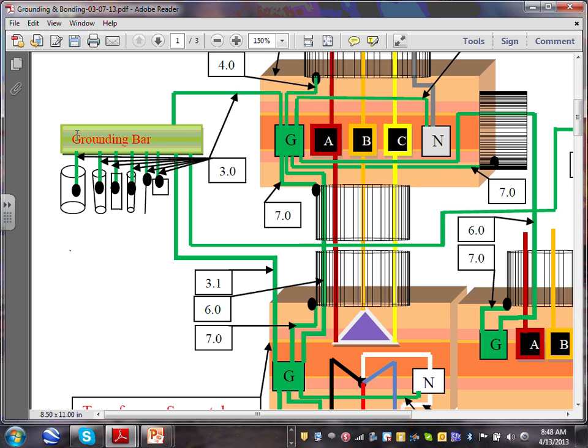So what I thought is to have, I'm sure you guys are familiar with a grounding bar. What they do in a bigger system like this is on the wall they will have that copper grounding bar, and they bring all these grounding electrode systems into that copper bar, tie it to it, and then they can ground the switch gear, the generator, the separately derived system. So that piece here gives you one single point where you can tie to the grounding electrode system external to the switch gear. You don't want to put it inside the switch gear, because every time you want to tie a grounding electrode system, you'd have to open the switch gear and tie to your switch gear. It's not a good idea.